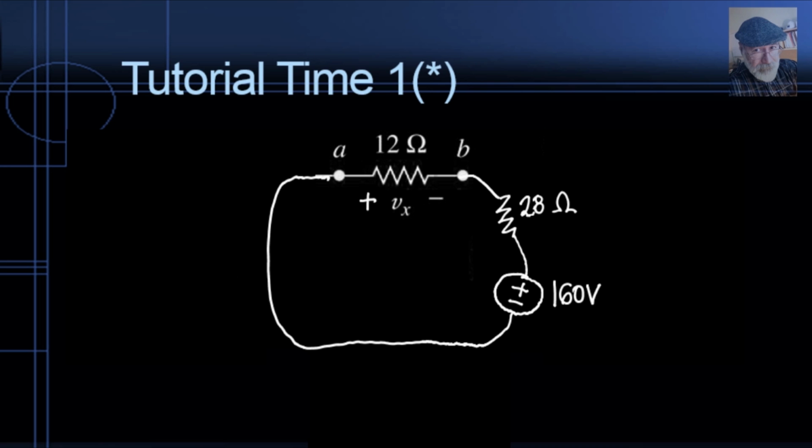This is our simplified circuit. And now, shall we simplify the 12 ohm resistor as well? We could, but we should not. Remember, don't oversimplify. Do not simplify the element into which you want to know what are voltages and currents. Leave it alone. Let's solve this circuit.